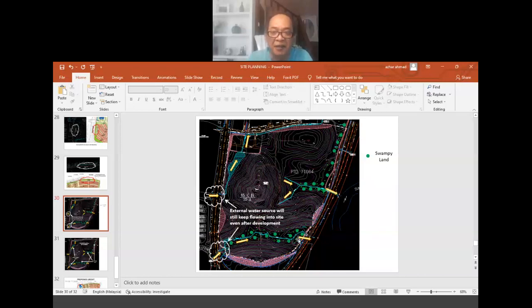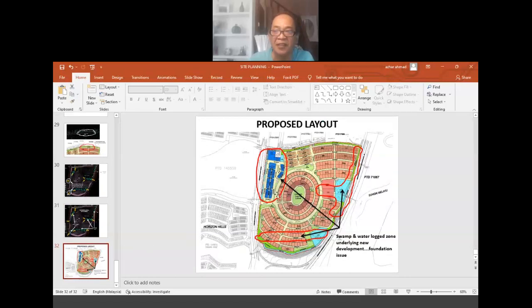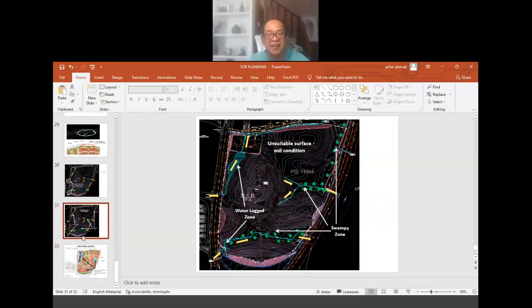So again, this would be information that we can share with the structural engineers, saying that these locations are quite unsuitable for normal pad foundation, and naturally you need to have specific foundation recommendations for this zoning. This would affect the foundation of buildings located within zones that we have identified earlier from our site inventory, and now we are doing the site analysis.